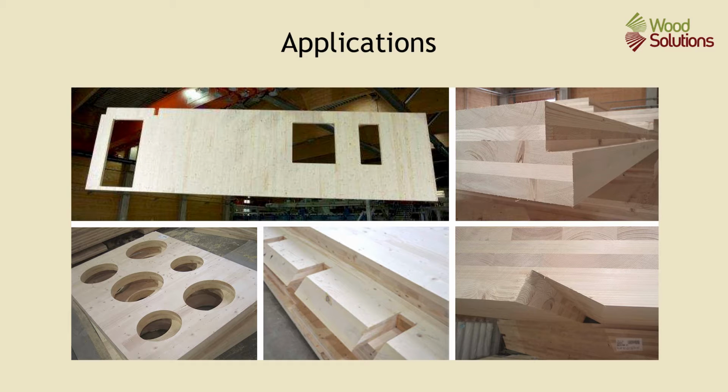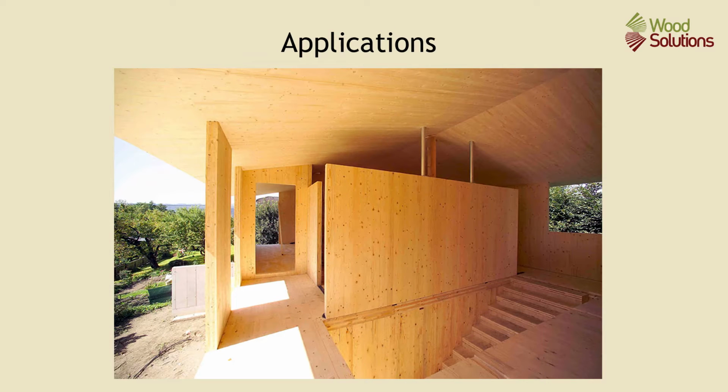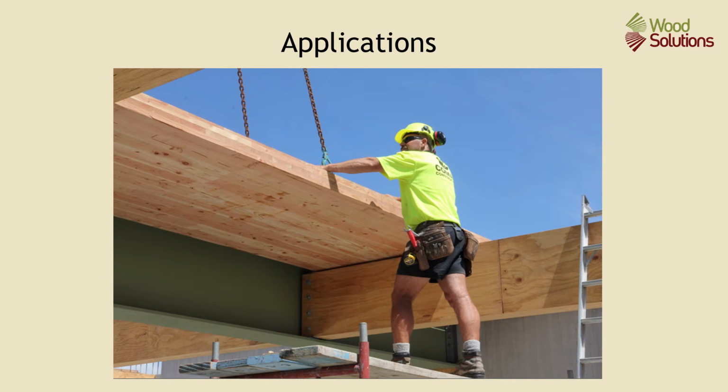Panels are made for the project and shaped with computer-controlled routers. These can cut windows in the panels, make ledges or form bevel connections. Pieces are then simply connected on site with screws. CLT panels can also be integrated with other construction systems such as glulam or LVL beams or steel or concrete structures. CLT production and use is just becoming established in Australia.